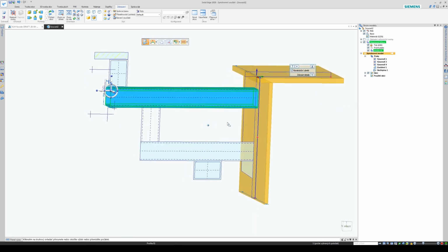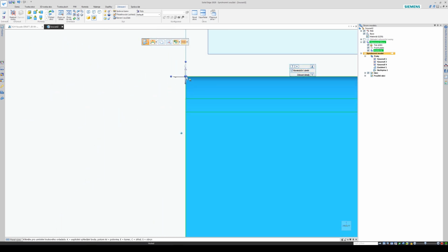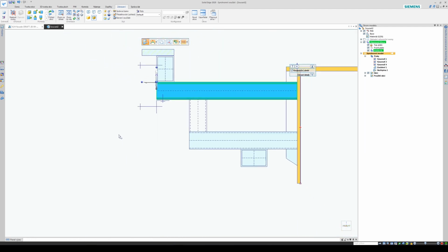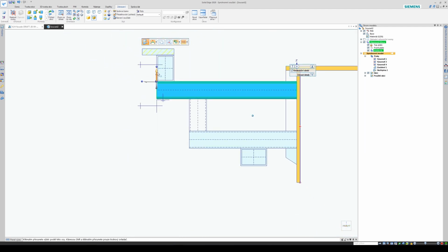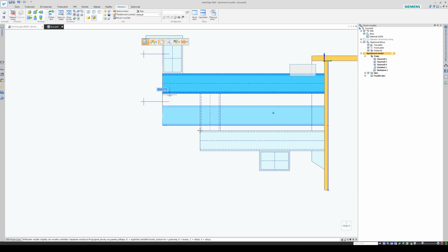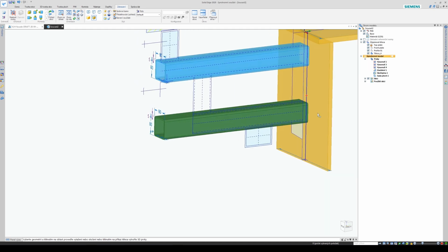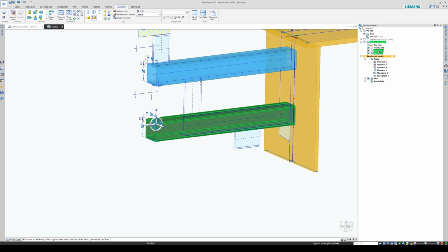Profile 1, just select it, right view, position this cursor here, and with Control pressed, just click the arrow and make a copy of the object. It's really created here. Let's just copy the name, paste it, it will be Profile 02.